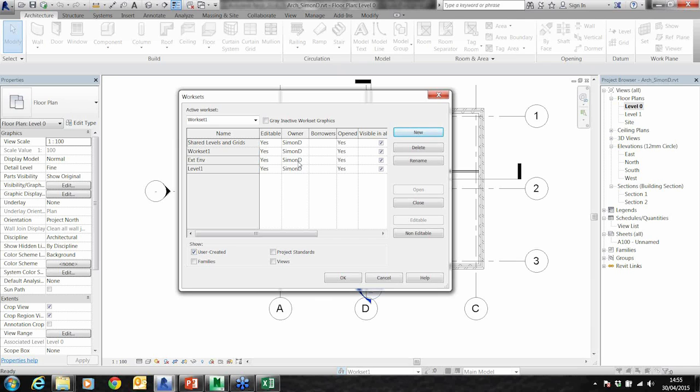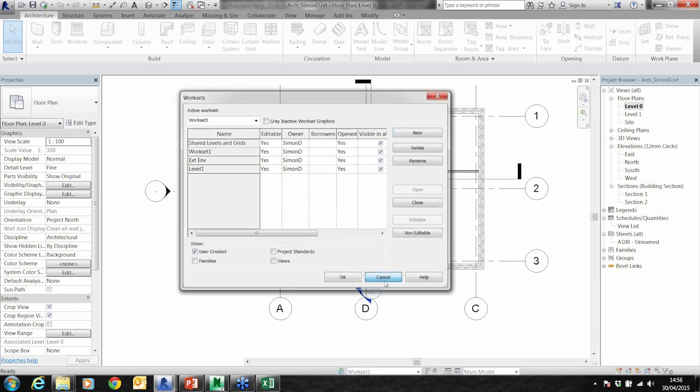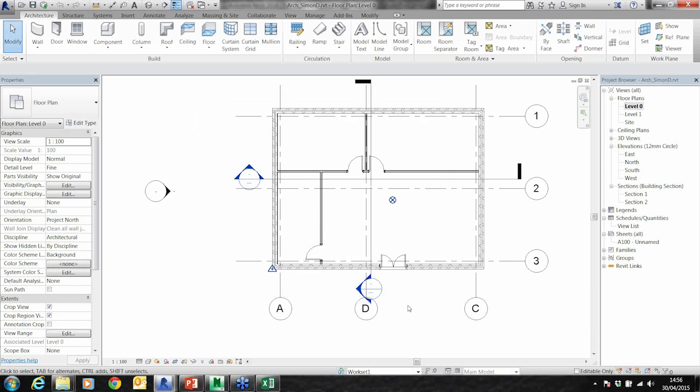It ships with Revit. It just needs configuring on 2 separate objects. So basically, it goes on 2 Windows 2008 R2 servers on both sites, and we can have local centralized files. Work sharing is a very complicated system in the background, but incredibly easy to use. And if you're using the borrowing method, it takes seconds to set up.